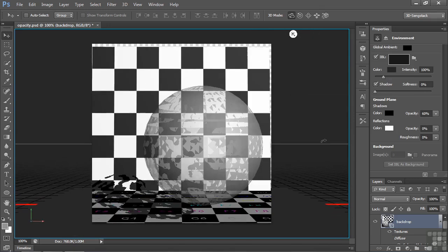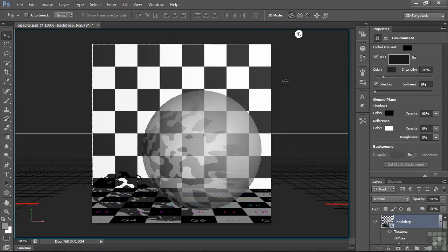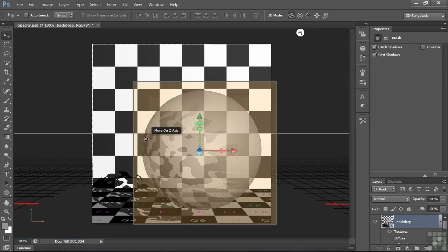Now you can overcome that by building out the walls here or putting walls around it. But for the most part, when you reduce the opacity, you get some transparency, and then you add some refraction. You're going to bend the light, and you're going to see that little checkerboard. So be aware that'll happen. You need to compensate for it in some way by building out the wall or putting an extra wall here, something like that.